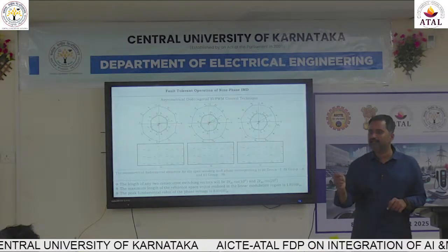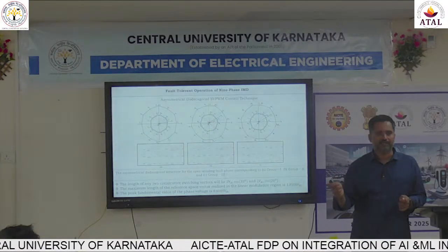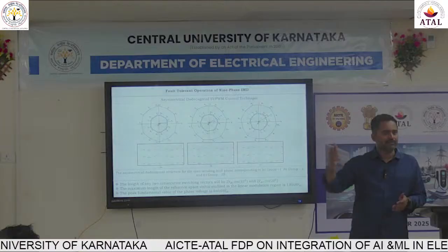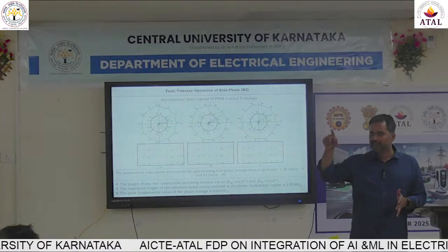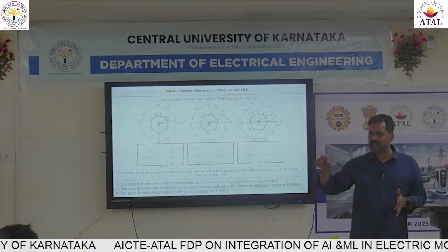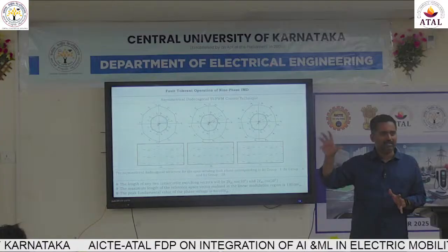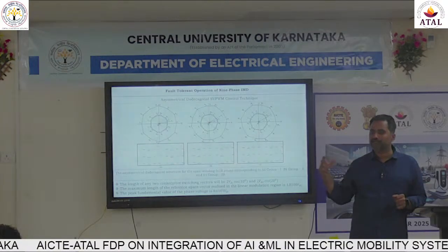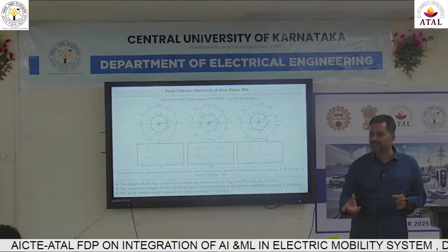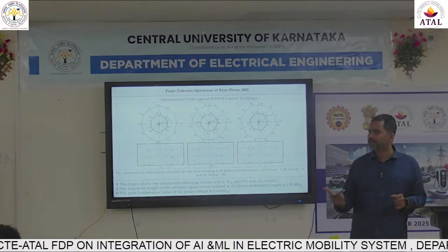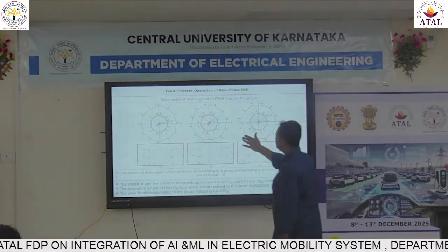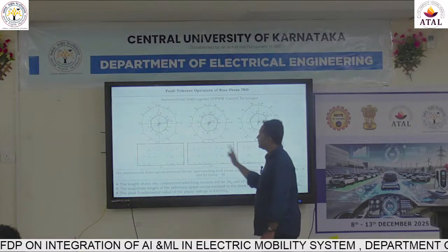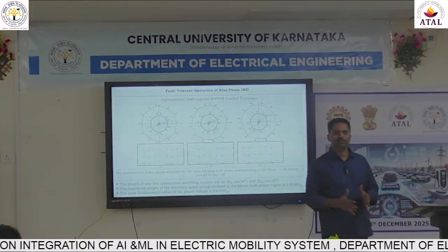You have seen space vector diagram implementations. You always say cos alpha, or sine of alpha minus 60 by sine 60. Some relations we bring in, in the symmetrical condition. In the asymmetrical condition, the magnitudes change based on the phase angles and everything. And when asymmetry comes, how do you get a balanced supply out of it? It is also going to be hugely complicated.